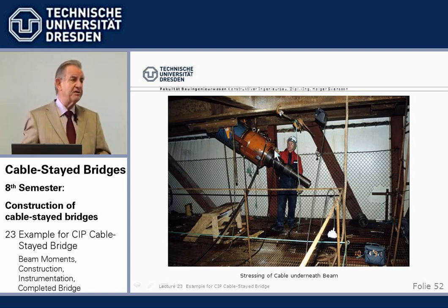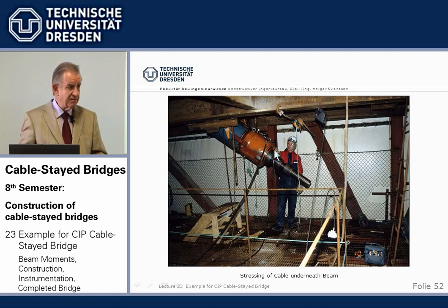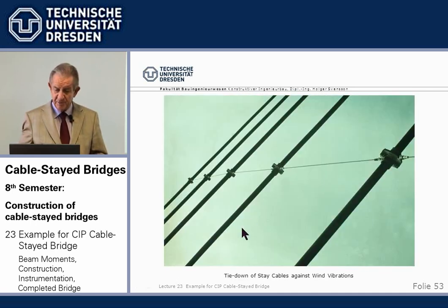Cables showed oscillations. So what we did is we tied them down with tie downs, strands, which works quite nicely but has two distinct disadvantages. A, it doesn't look nice. B, it makes it difficult to inspect the cables by a carriage which runs on the stay cables.